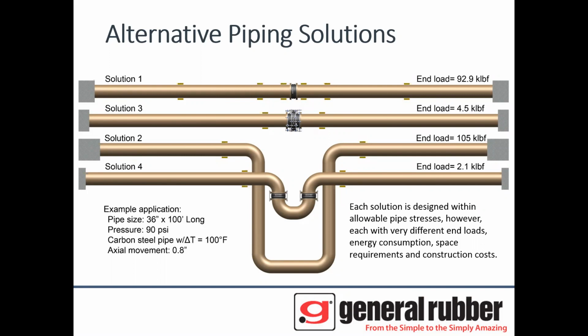So the first example, solution 1, uses traditional expansion joints with numerous guides and main anchors. The rubber expansion joint absorbs the thermal movement and the anchors hold back the pressure thrust force. In solution 2, you can see that the end load is 92,000 pounds.